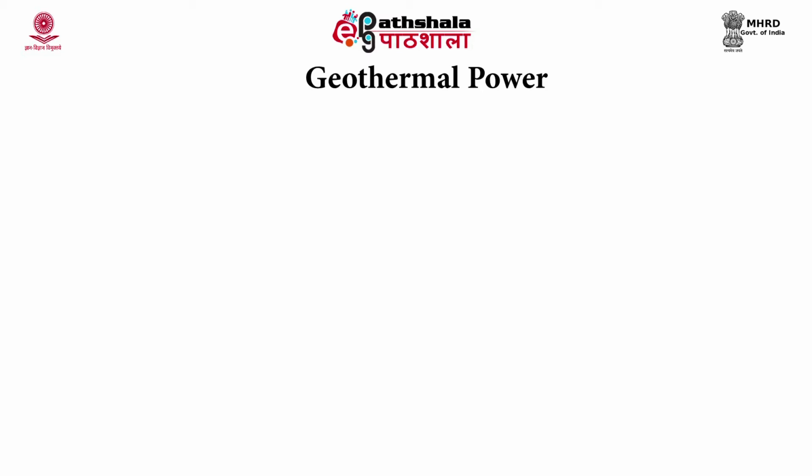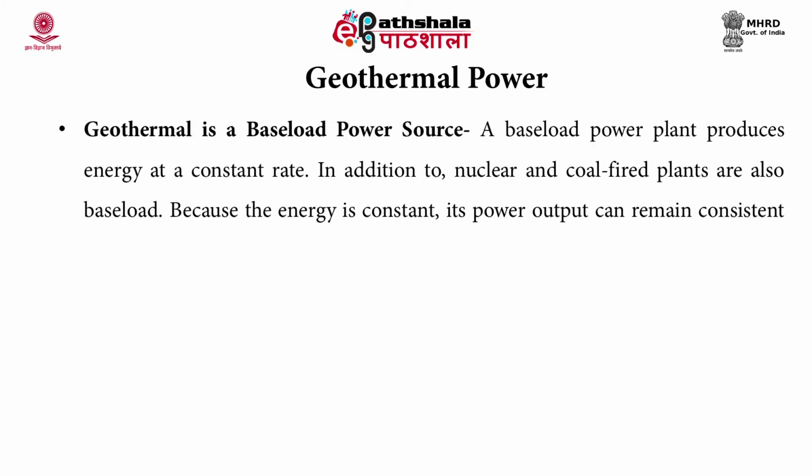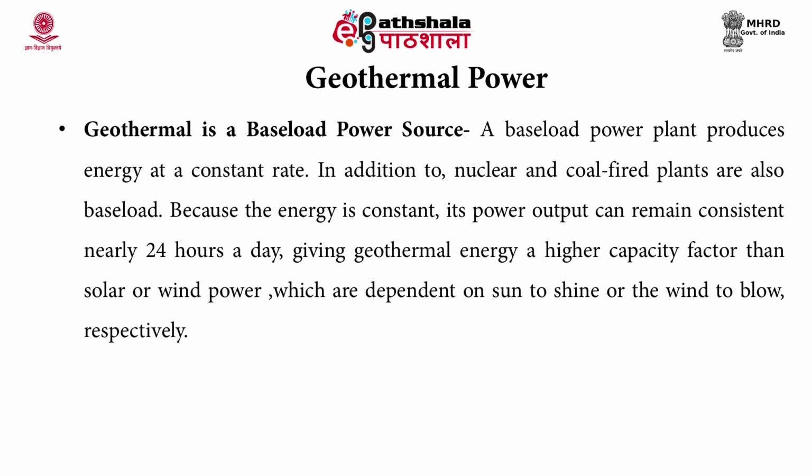Let's see in detail about geothermal power. Geothermal is a base load power source. What is a base load power source? It is a plant that produces energy at a constant rate. You can say nuclear as well as coal-fired plants are also base load power sources because they produce at a constant rate, while solar energy is not. Because this energy is constant, the power output can remain consistent nearly 24 hours a day, giving geothermal energy a higher capacity factor than solar or wind power, which are dependent on the sun to shine or wind to blow.